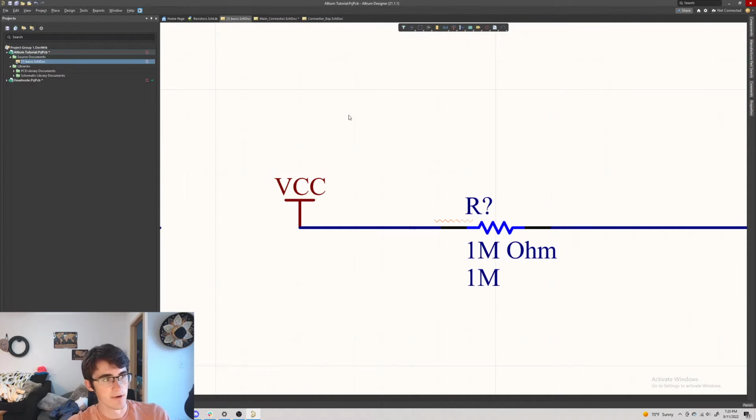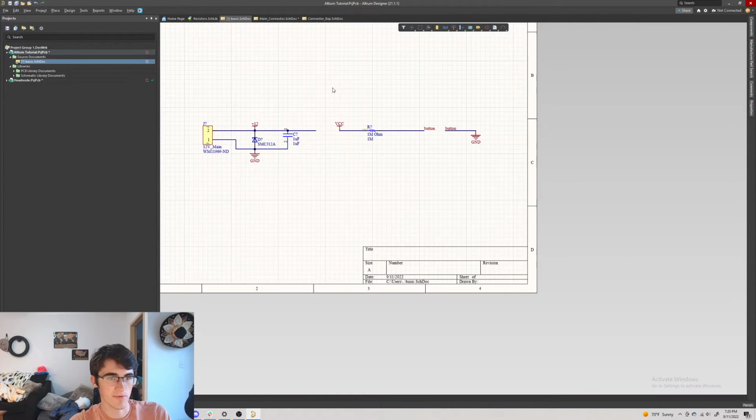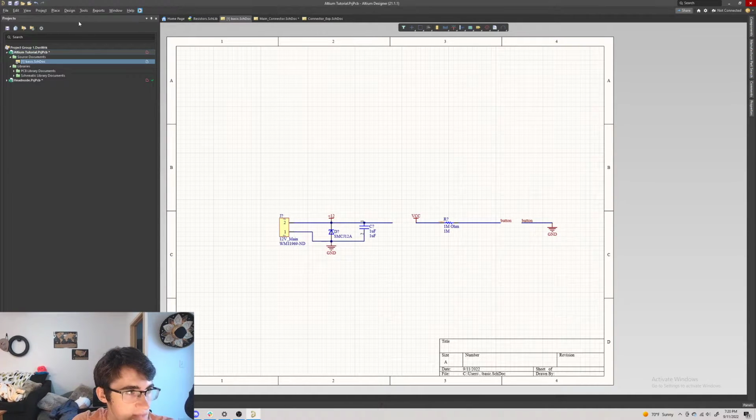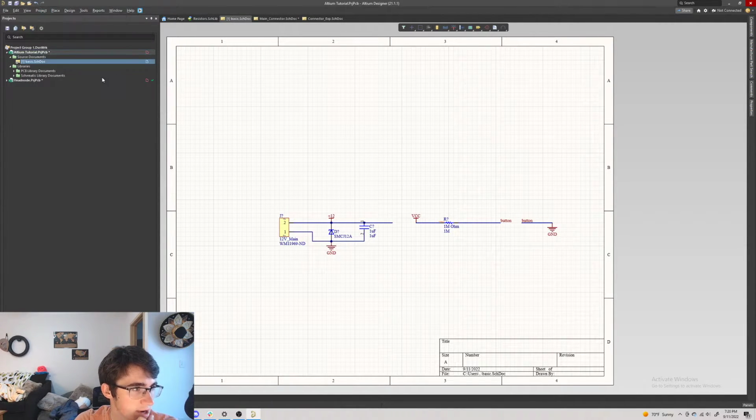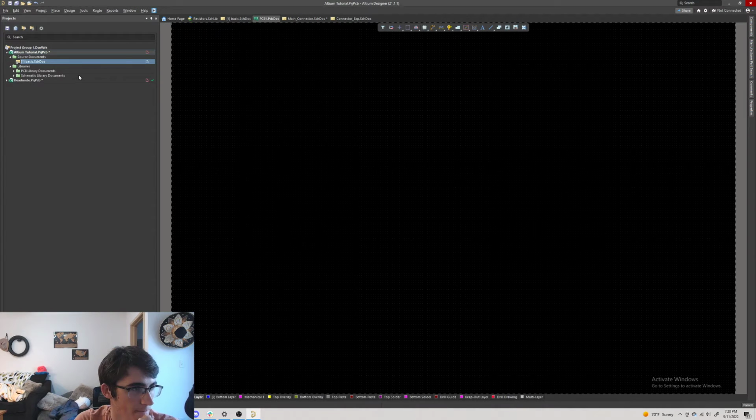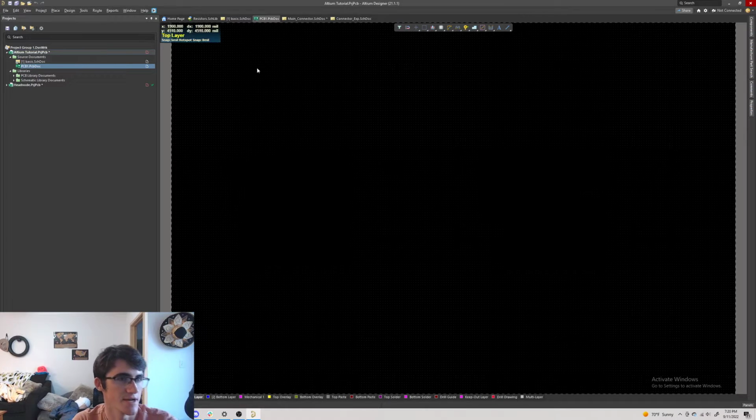But so let's say, cool, okay, we have our circuit done. What are we gonna do next? So what you want to do is create a PCB file and start designing your PCB. So let's see, I haven't done this in a while. I think if you do, let's see, if you do add new PCB to project, you can see here that PCB1.PCB.doc is created.